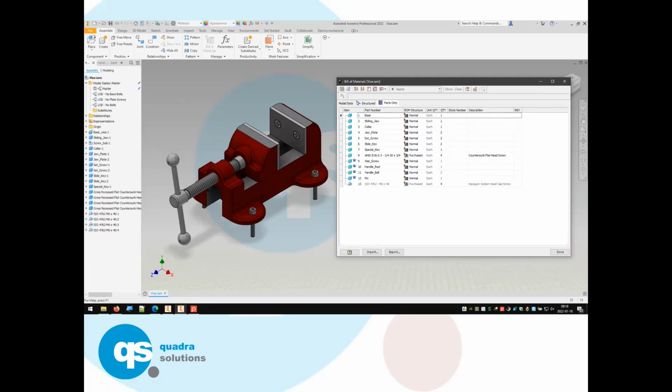We still have design views, which is looking after component visibility, component color and camera, spinning the model, making something invisible, so parts omitted for clarity. That still exists, but I need to see through the door to see what's on the inside of the cupboard. Camera position, colour. We only modelled the bolt once, but you could have a green bolt, a red bolt, and a blue bolt in the assembly.